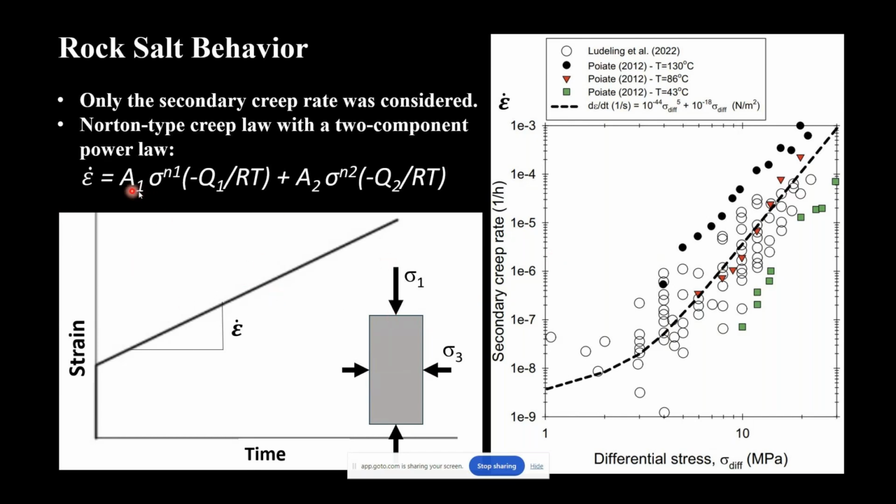And to determine A, to calibrate, let's say, this expression, I used values that are published in the literature. In this reference, Ledling 2022, the authors compiled a large number of triaxial creep tests from halite samples all over the world and under different temperatures.